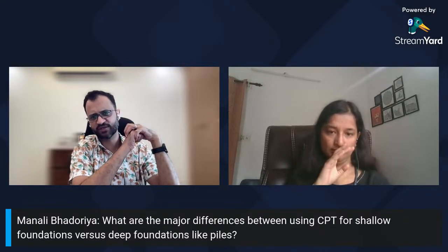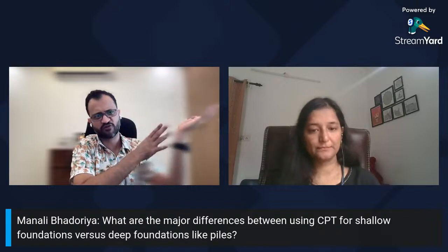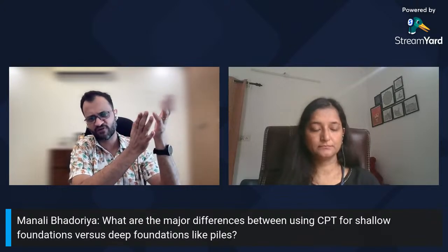Question is from Manali Bhadoria. What are the major differences between using CPT for shallow foundations versus deep foundations like piles? There's no difference. CPT is an investigation tool. I'm not sure what the import of your question is, but you can use CPT data both for design of shallow foundations as well as for design of deep foundations like piles. It's applicable to both possibly.